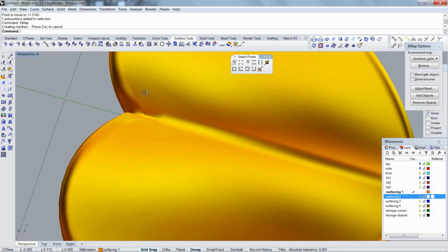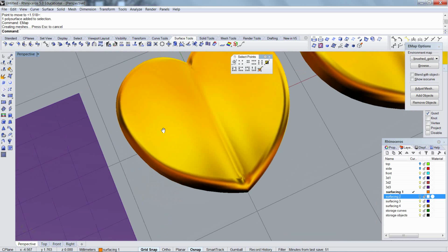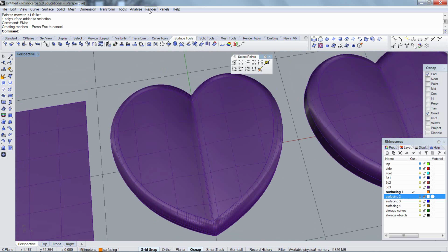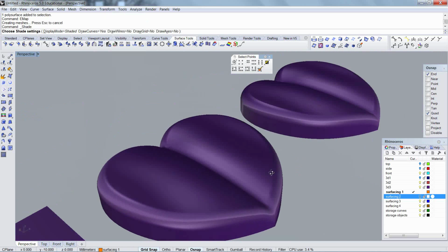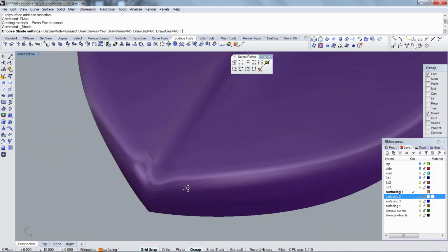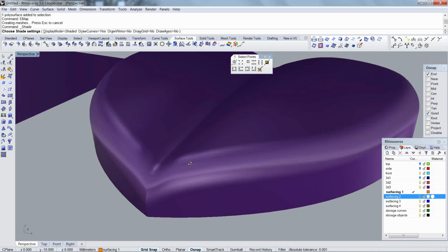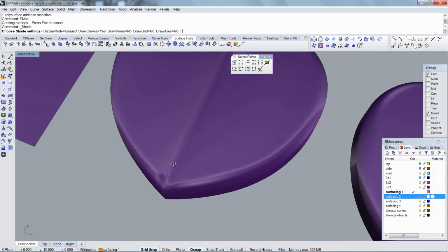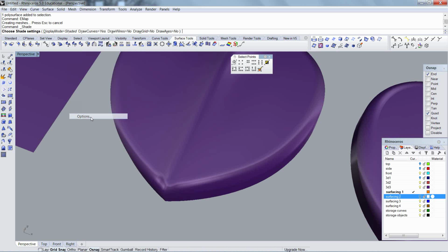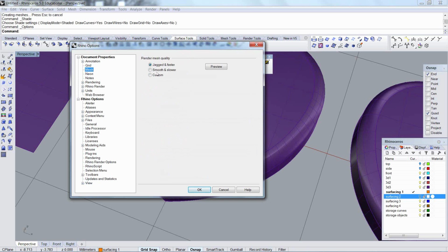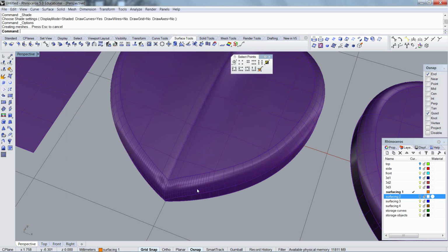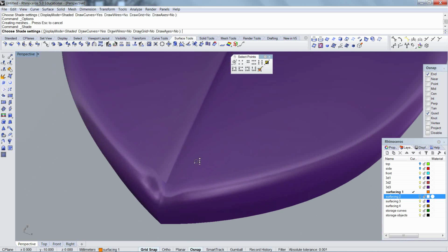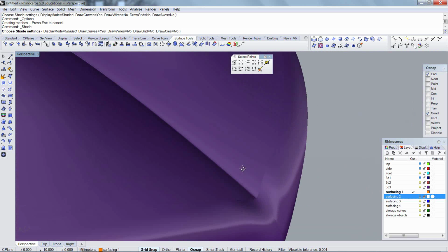That's really a display. It's not really in the model. That's in the display, I believe. Yeah, if I go into shade mode, you can see that there is a seam there, but the strange fracturing you see are meshes on the surface, which if I set the surface mesh higher to smooth and slower and hit the render shade again, there won't be any of those in there.